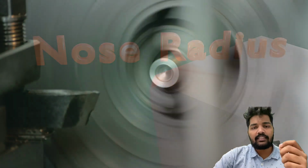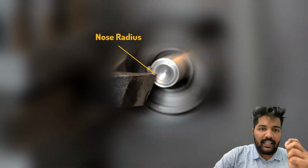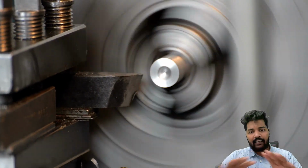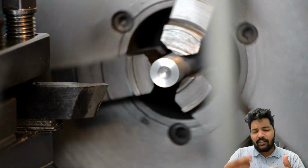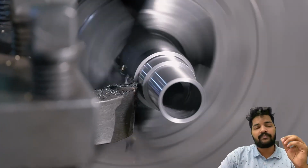See, the nose radius is a rounded curvature at the tip of the tool's nose. It serves multiple purposes such as enhancing tool life by distributing the cutting forces, reducing the likelihood of chipping, improving the surface finish of the workpiece overall.